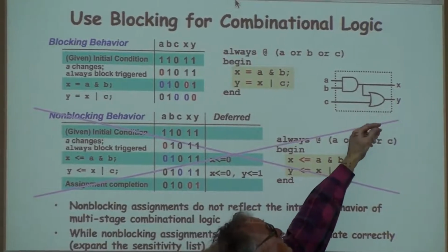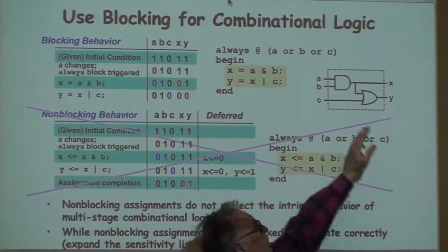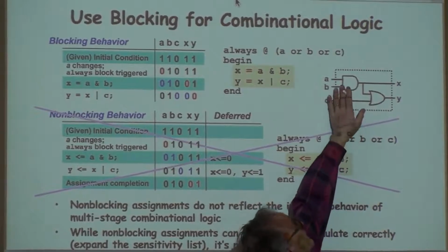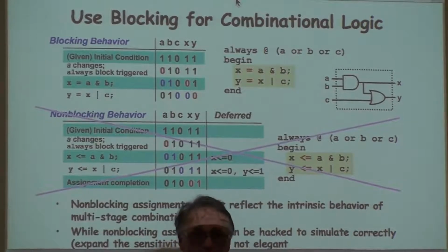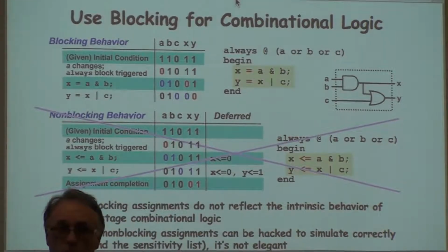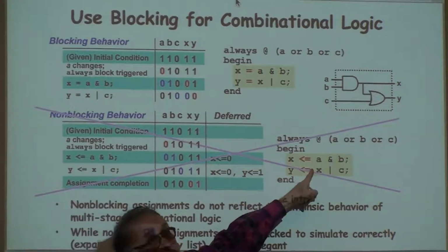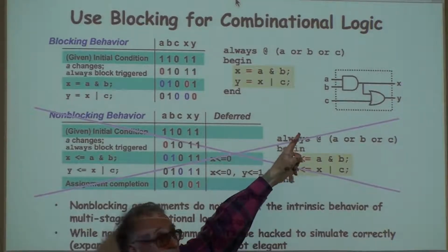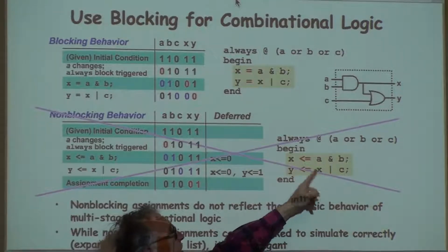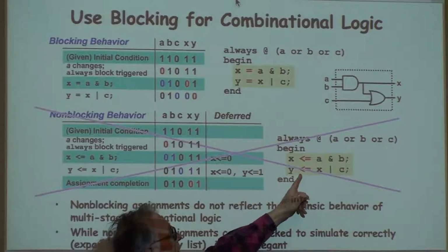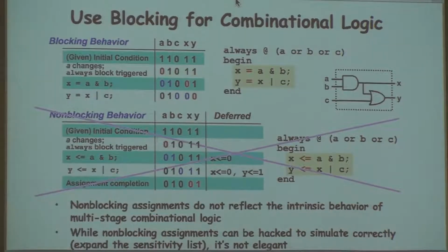And so what you want to synthesize, because there's no clock here and therefore there's no sequentiality, is a combinatorial circuit that takes A and B and then combines them with C, and the output here appears effectively instantaneously. If you did this with non-blocking assigns and expect that circuit, then you're doing something different. You're taking A and B on one clock cycle and C on the next clock cycle and combining them. Or something.